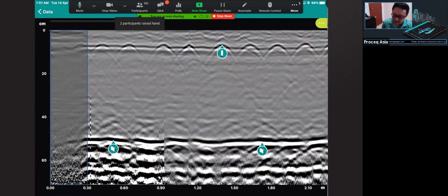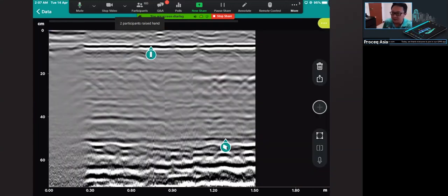Just now at the beginning of the video, we noticed the concrete has very serious deterioration at the bottom of the column. At least the reflection may present how the concrete condition is in the radar diagram, right? From the left-hand side, it really gives you an indication how bad the concrete is, especially as we couldn't see the total reflection from the back wall. This is something we can see from the radar diagram. So how about a cross-polarization measurement, right? This is a cross-polarization measurement. For example, we scan and just rotate the view 90 degrees, and we have this kind of measurement result.